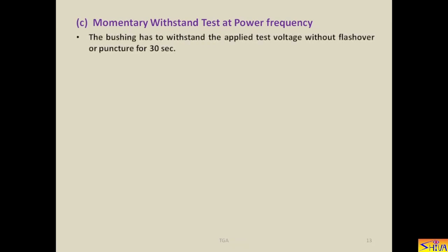Then momentary withstand test at power frequency. Bushing has to withstand the applied test voltage without flashover or puncture for 30 seconds. Now how much should be this voltage? That also depends on the rating of the bushing.